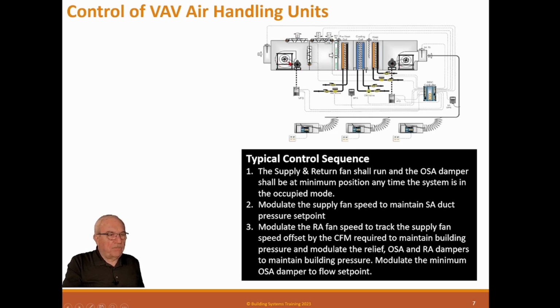Now that's not perfect, but it's the best, easiest sequence to do this. Some people will put flow meters on these fans and track through these flow meters, and that's okay. But the problem is they normally try to use vortex flow meters, and a lot of them are just a little plastic tube around the inlet, the vortex inlet. Those aren't very good. They break, they don't last, and they're not very accurate. Now, if you buy a really good quality vortex flow meter, that's okay. But it's much easier just to set it up to have the VFDs track them, and that is prefaced by one condition.